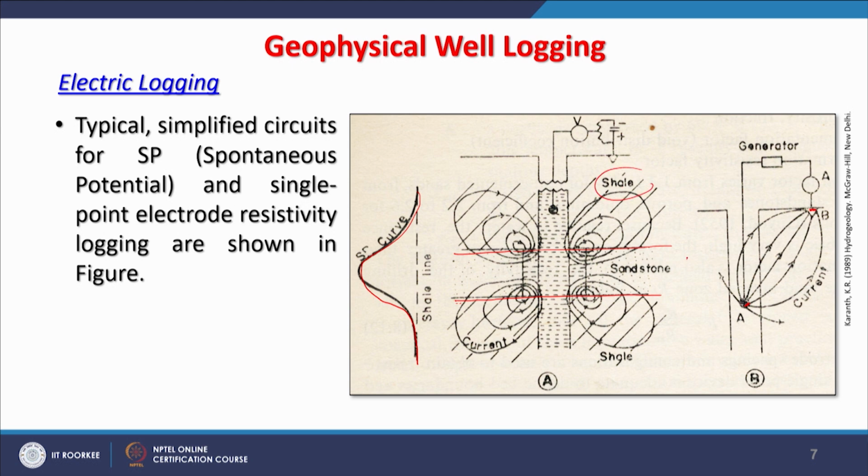In this example, it becomes confined aquifer conditions, and this is what the target is. So, the SP curve will indicate which area might be confined aquifer conditions, and through the litholog you can make sure that this is what is happening.